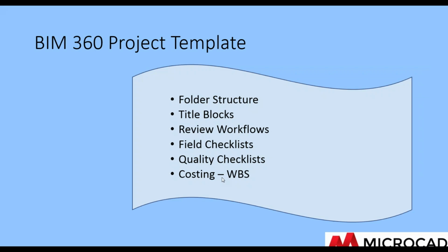Many of the things that have to be set up for a project are in the template. So if you can do it once and reuse it, you'll save time. Say that you have a contract to build 3 elementary schools in Connecticut. They will all have similar design features, review processes, and commissioning requirements, so you create a BIM 360 project template configured for that job. Then create 3 production projects based on that one template. Those of you who've worked with Revit know that setting up a good Revit project template is key to being productive. Same thing here. Now let's look at how we would configure a project.